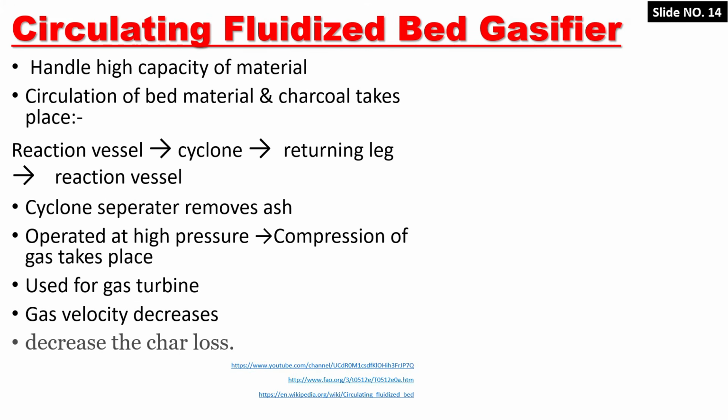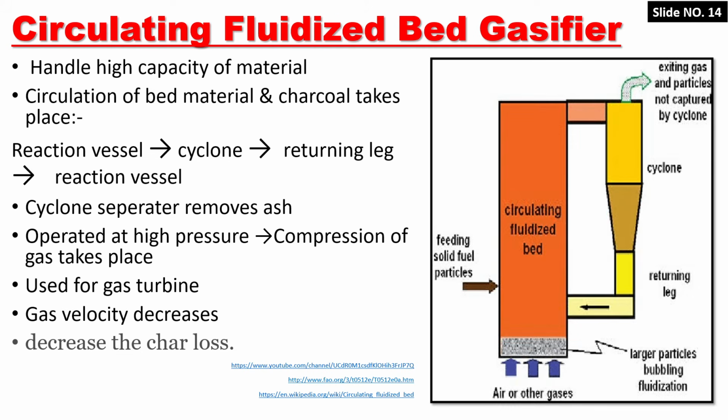The first type of fluidized bed gasifier is the circulating fluidized bed gasifier. A circulating fluidized bed gasifier design operates at a high velocity and incorporates recycling of the char and bed material, resulting in complete mixing regardless of feedstock size. Generally, the circulating bed designs are more flexible but are still limited by the amount of very fine material that they can process.